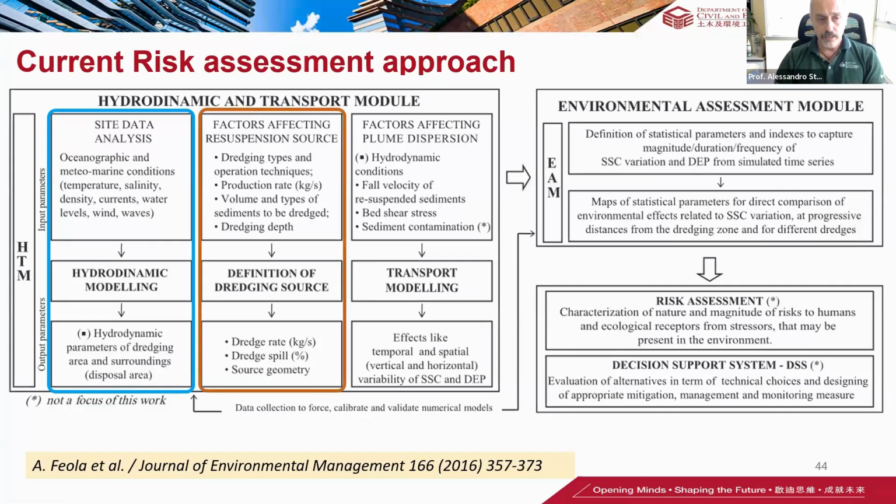Then you have to, of course, define your dredging source. So the dredge rate, the dredge spills, the source geometry, what type of dredging duty cycle you are using. And of course, you then need to couple this and produce some sediment transport modeling to evaluate the dynamics of the sediments.